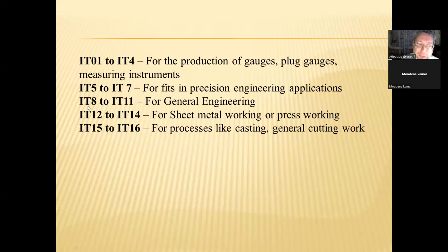In general engineering, we use IT grades from 8 to 11. From IT grade 12 to IT grade 14 for sheet metal working or press working.